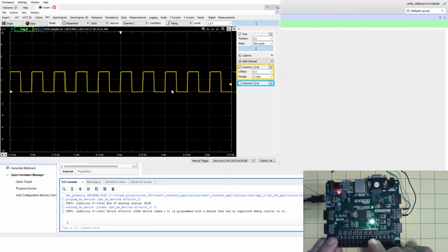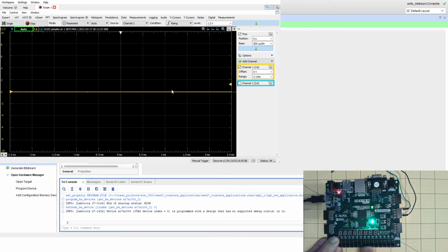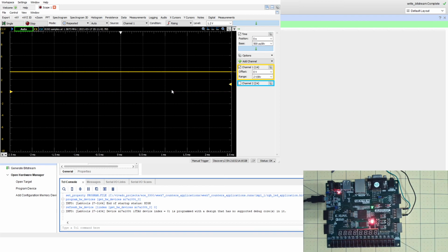And of course, again, if you put that switch 8 in here, let me just do reset, you're going to get the brightest color here because that 8 is actually the 256, and any other numbers in here, you're going to keep getting the same exact color. And let me just show you that on the red, for example. Let's say reset, and then I'm going to go to the 8, and I'm going to do red in here. I'm writing it, and you can see on the diagram in here, it actually moved to 1 because it's 100% duty cycle. It's always on.